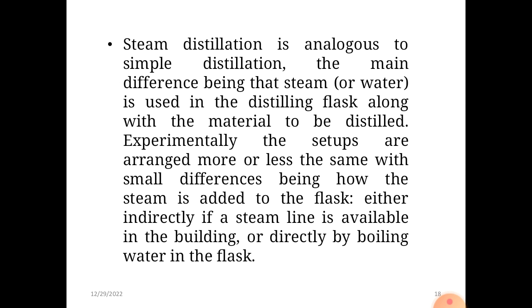Steam distillation is analogous to simple distillation. The main difference is that steam or water is used in the distilling flask along with the material to be distilled. Experimentally, the setups are arranged more or less the same, with the small difference being how the steam is added to the flask, either indirectly if a steam line is available in the building, or directly by boiling water in the flask.